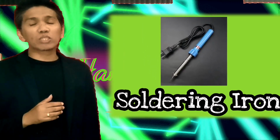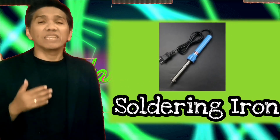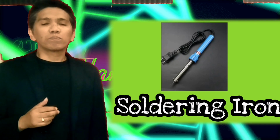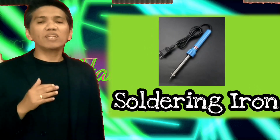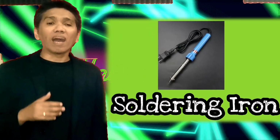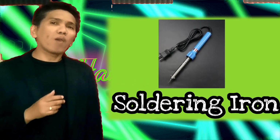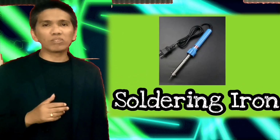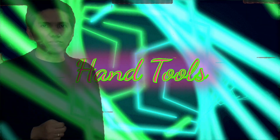A soldering iron is composed of a heated metal tip and an insulated handle. For electrical works, wires are usually soldered to printed circuit boards, other wires, or small terminals. A low-power iron, 20 to 30 watts, is suitable for this work.